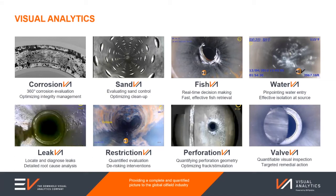The more recent advent of polymer-based sealants or gels, I've seen a number of cases where they've worked tremendously successfully. But in all of these cases, and my history goes back, I had 5 years of doing very specialized leak detection using ultrasound. The companies making the sealants or the remedial solutions, they were our best friends as the diagnostic company, because we helped show them exactly where to place it. If you put any of these in the wrong position, it just simply doesn't work. The device is probably doing what it's meant to be doing, but it's just not at the right location to get maximum effect. So I think it's a bit of a mixed answer, but really, as long as you've got a range of options, it's more a case of narrowing it down and making sure you put it exactly where you want it and where you need it.